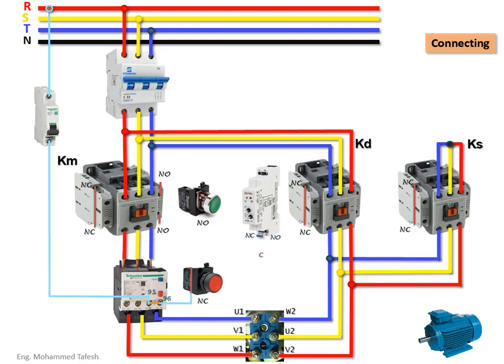And we don't forget this important element that we talked about previously, which is the electrical lock. Its function, as we mentioned, is that as soon as we press the start button and lift my finger from it, the circuit turns off. But with the lock, when I raise my finger, it will keep the circuit running because it will take another path through this latch or lock and keep the circuit in the running state.